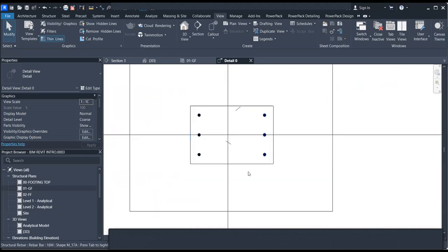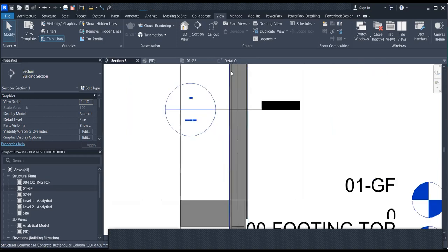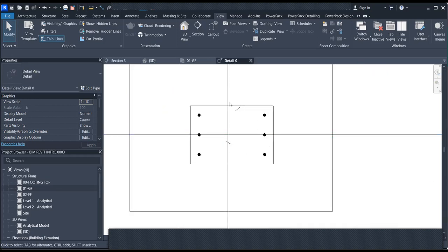So now we have the bars. I can go ahead and place some more bars on top here. But before I do that, let me place my stirrups here, okay? The links, before we add some more bars there. So the links can again be placed still under the elevation, or you can place your links within here. Let's do it here this time.